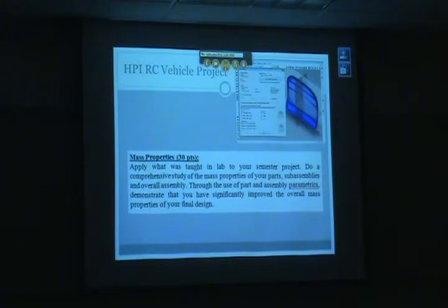So as you're taking your car apart, think about just going in and finding an accurate scale, setting the part down, weighing it, using your calipers to measure the part, create it in CAD, and then when we get to the mass properties part of it, all you'll have to do is enter the material type, ask for it to calculate it, and then you'll be able to compare what the CAD system said to the actual weight measured by the scale. And hopefully, by the end of the semester, when you set the entire car on the scale and you ask for a full accounting of the mass properties of your CAD system, you'll be able to get that.